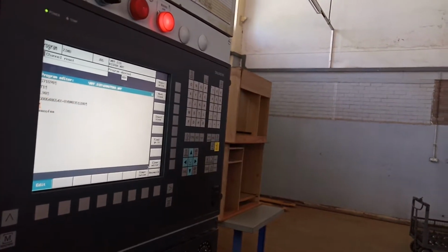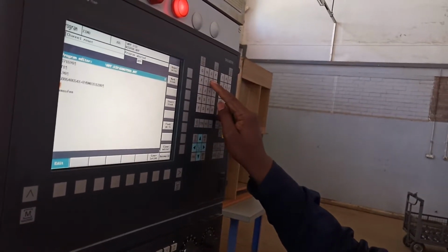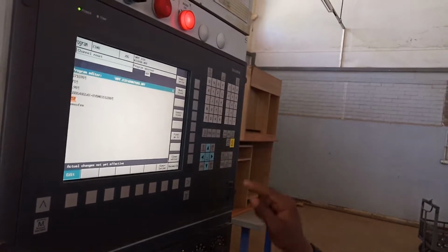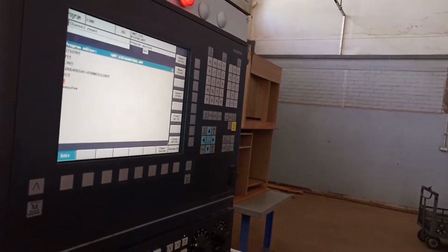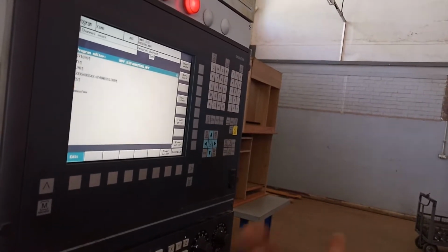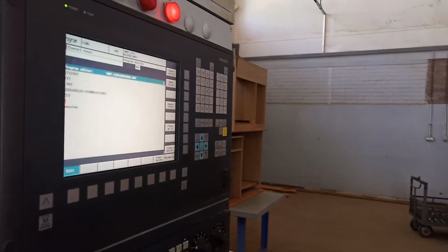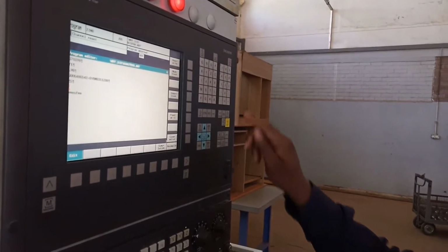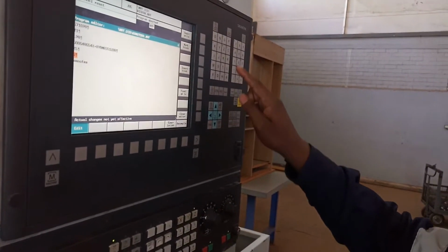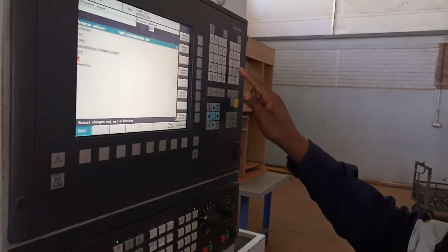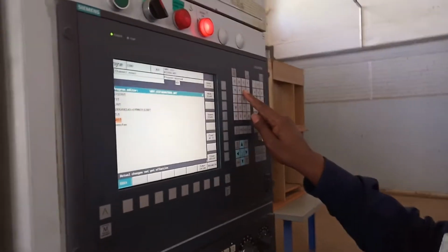And then I press input, and I want my spindle to go 5 millimeters above the job, so I put Z5 and I press input. Right now I'm machining aluminum, so I don't need coolant, so I'm gonna skip M07. So I'm just gonna go to G01, start cutting. G01, and take my depth of cut.